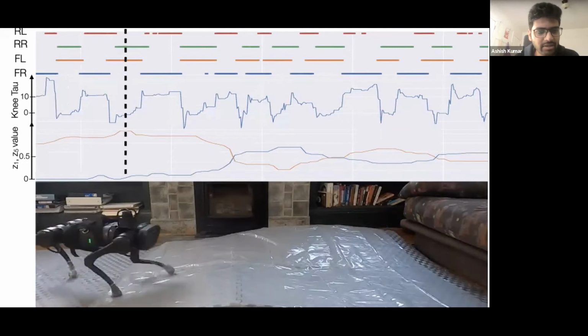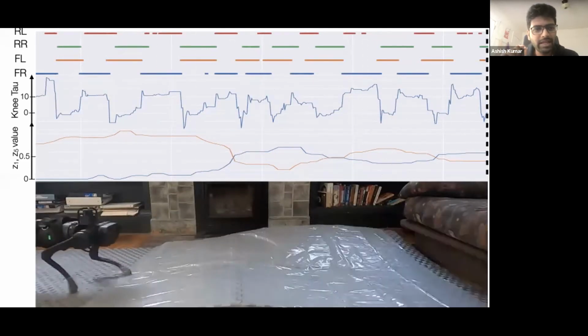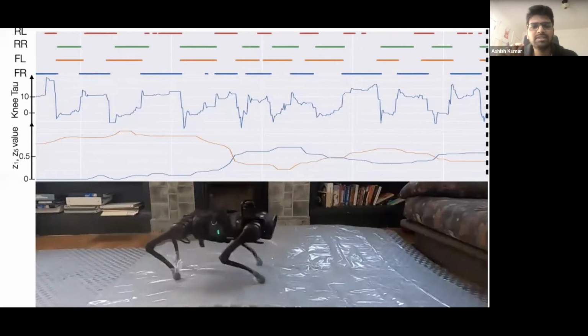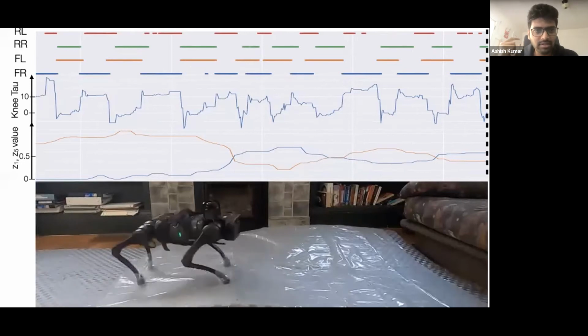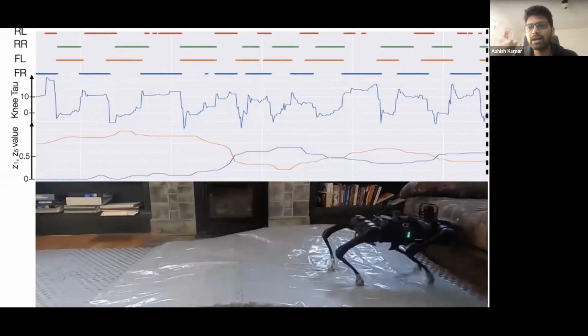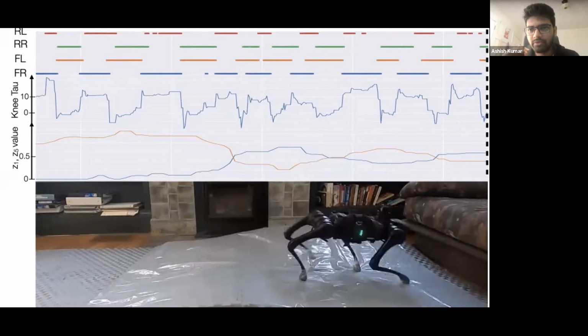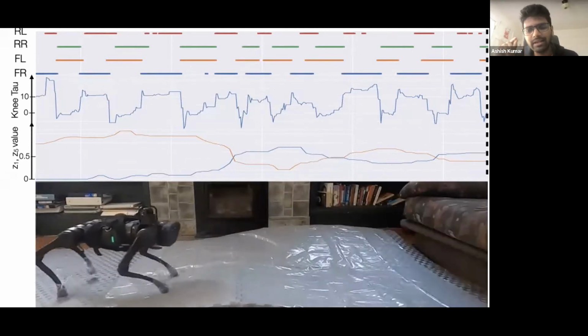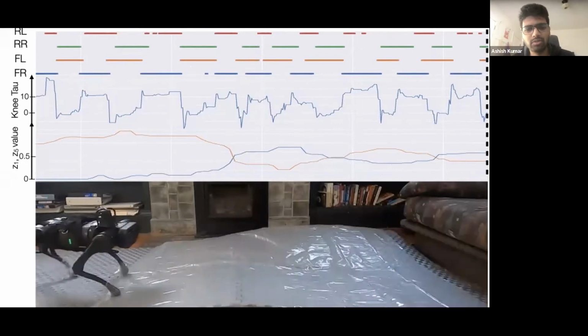And we see that when I run this, you will notice that the moment the robot starts slipping, the extrinsics vector captures that fact and continues capturing it. And that is what enables the torque and the gait pattern to go back to normal. Note that the robot entered the slippery surface before, but it captures that it is slippery only when it actually started slipping, because that's the only signal the robot has.